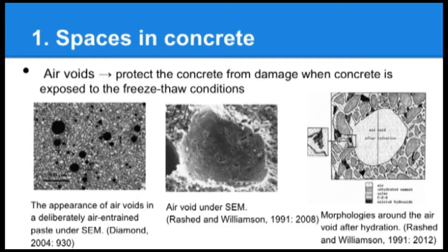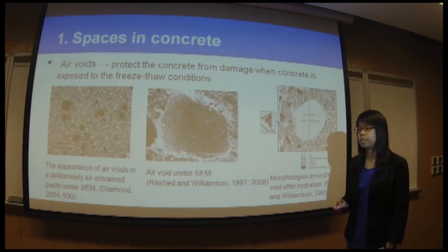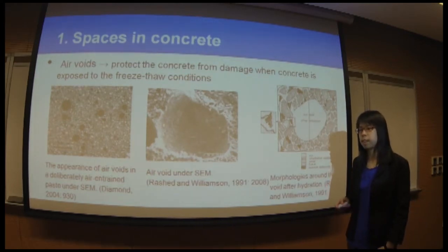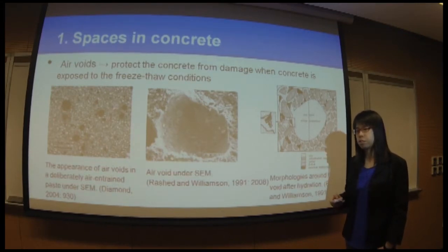Spaces in concrete. Other than the ITZ, there are some air voids in concrete, and the function of the air voids is to protect the concrete from damage when concrete is exposed to freeze-thaw conditions. Actually, the air voids usually occupy about 15% of the non-aggregate space.